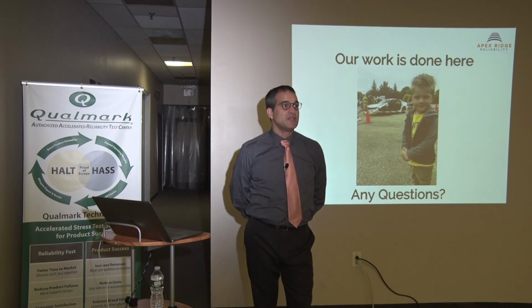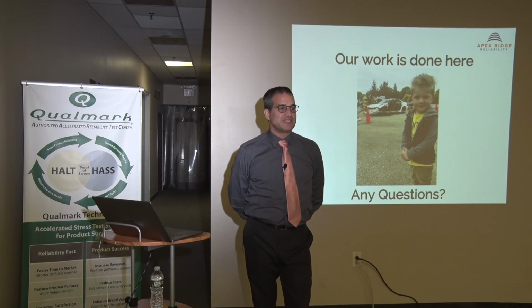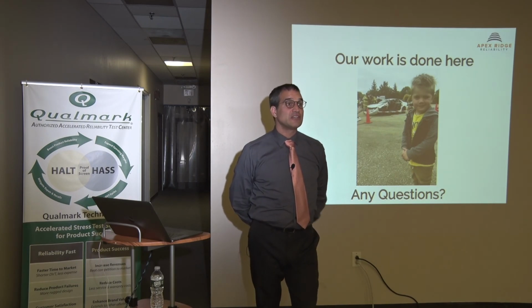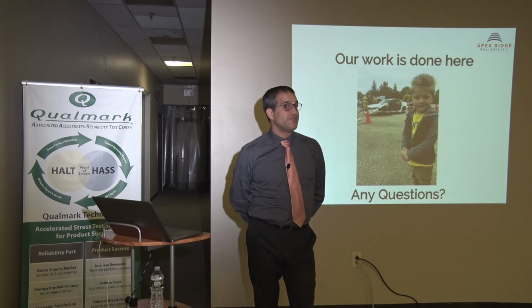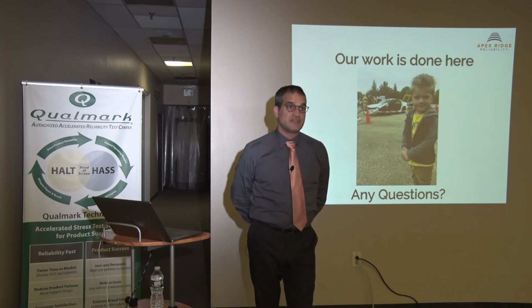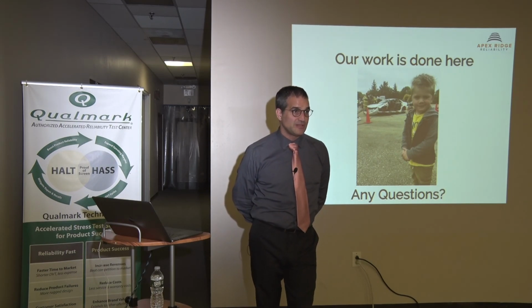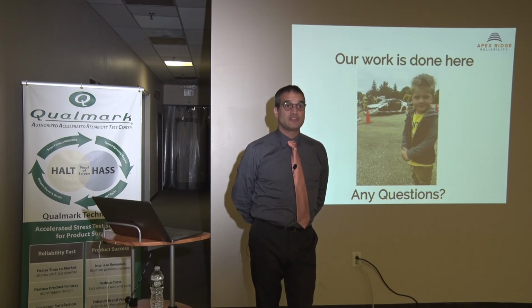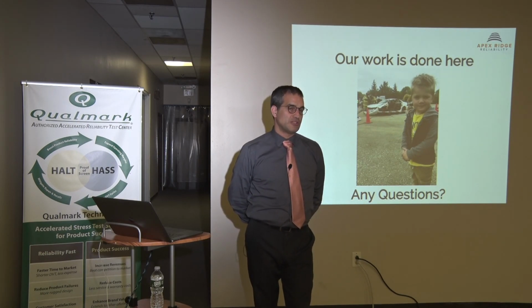And that's what you've given up for the speed of getting that very valuable information. So Weibull analysis input data sets are based on the idea of percentage that passed and percentage that failed, and looking for how those behaviors change and characterizing and projecting it out. So I would be very hesitant to use any HALT data for anything like that, because that's not its purpose. It's possible, but the research project you would have to do in advance would be quite tremendous to make those correlations. And you would be better to do other more traditional types of reliability tests to generate that information.